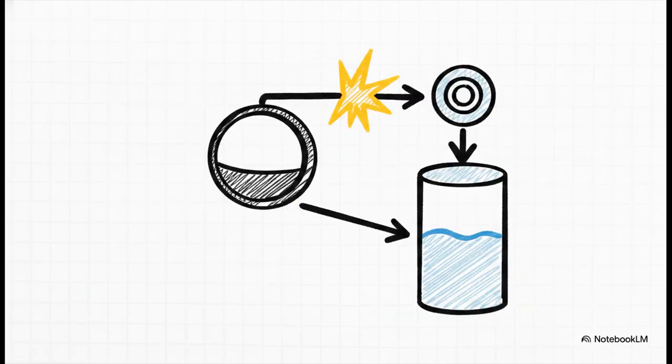So fundamentally, a pressure transmitter is just converting force per unit area into an electrical signal, usually giving your controller that standard 4 to 20 milliamp output. And yeah, sure, it supplies the primary process variable, or PV, for your basic pressure loops. But here's the kicker. It also secretly feeds a ton of your flow and level measurements too. We'll be looking at that throughout this explainer. Because honestly, the exact same physics used to measure pipe pressure are used to measure flow across an orifice plate, or even to calculate the liquid level in a massive storage tank.